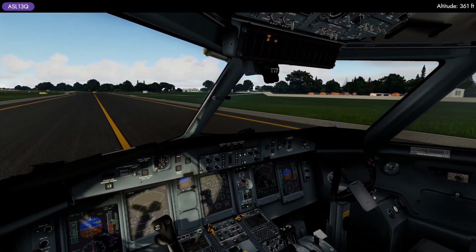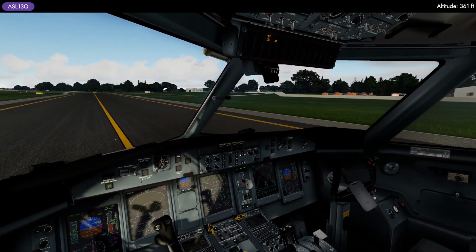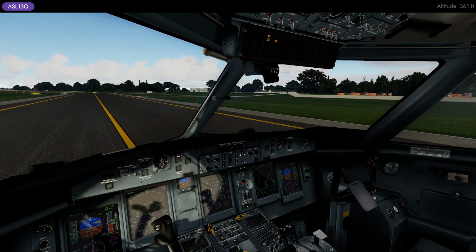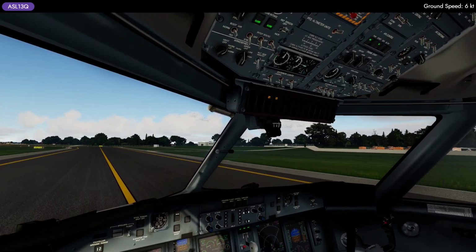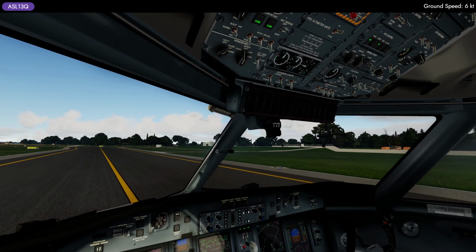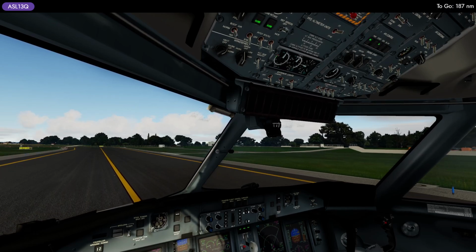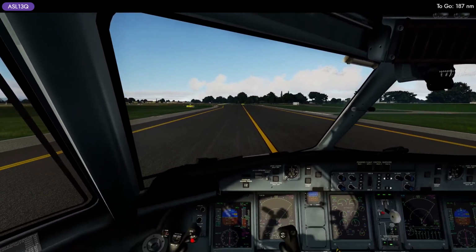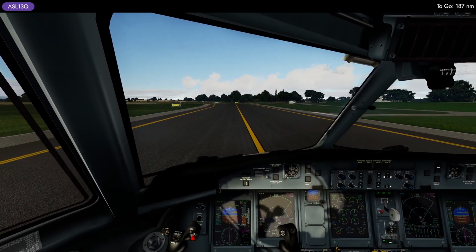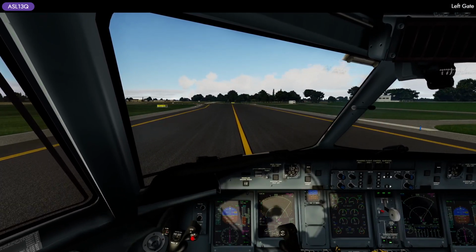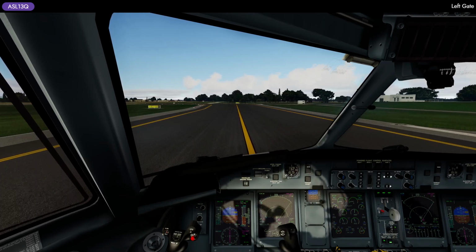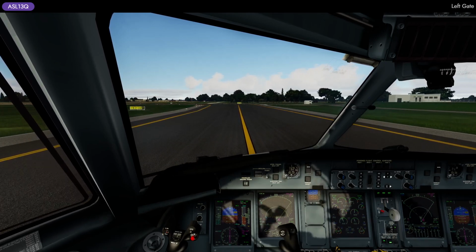I like to turn on my lights, also turn on the standby and the pitot heats. Very important, don't forget it. You get the inaccurate readings, the pilot will then disengage and you have a lot of troubles just because those little static ports get frozen up.